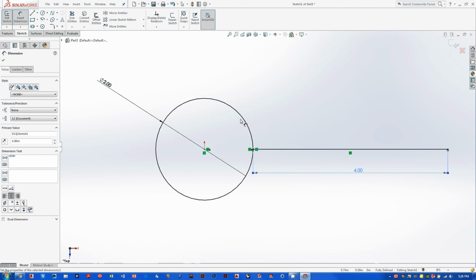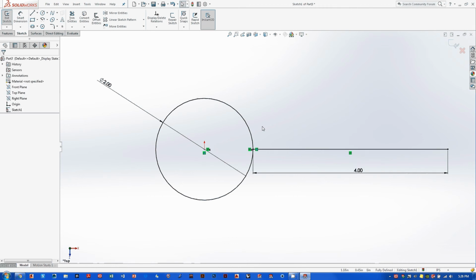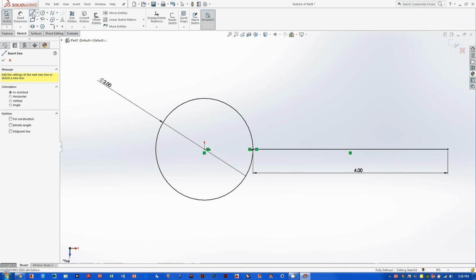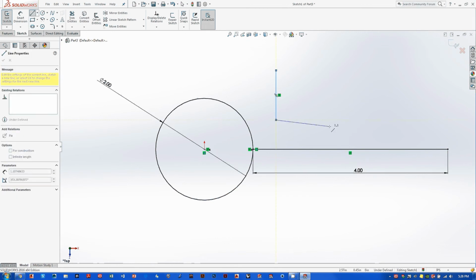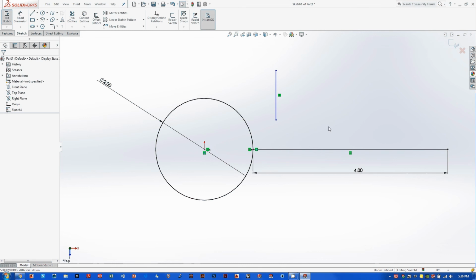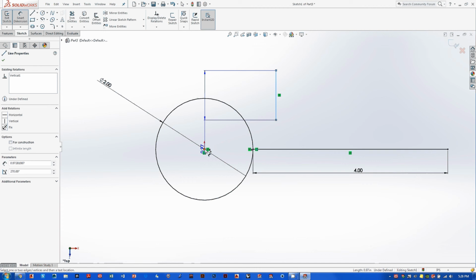Alright? So, there's other things you can do. I'm going to get another drawing tool out and we'll play around with adding some dimensions to show you how that can work. Okay, let me hit escape to drop the Smart Dimension tool. And I'm just going to grab a line tool and I'm just going to click in space, just anywhere. Just draw a straight line. So, the other way that Smart Dimensions can be used is for the purpose of moving things around on your page.